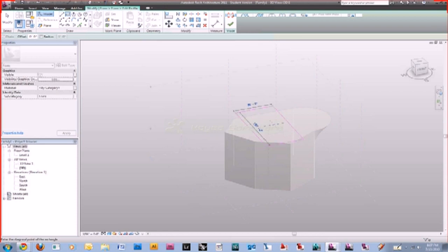All right, you can edit the vertical faces, but it's not a profile, so you can't edit profile. It doesn't know where the reference plane is, and without a reference plane, you can't edit easily anything. Yeah, it's kind of based on how you created it too. If it's an extrusion, then you can edit sort of the profiles that made that extrusion.